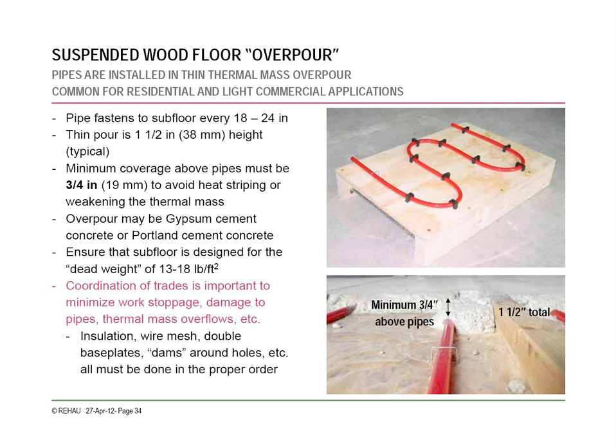Okay, we're going to switch real quick here into a suspended wood overpour, which is the other type of wet installation that we were talking about. You can see here on the bottom right, it's common to have them with sleepers if you're going to be putting a wood floor over them. Otherwise, just a standard poured slab over the wood.